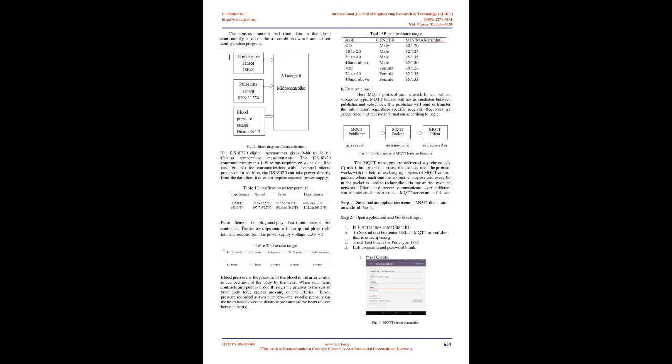Sensing node. Each sensor node is connected with a microcontroller and a power source. The sensors will require a limited source of energy. The sensing nodes will sense physical data, then monitor all conditions, and after performing small processing operations will transmit data to other sensing nodes and the network. Transmission technology. Transmit data over the network through a Wi-Fi module with the help of the Message Queuing Telemetry Transport, MQTT protocol.